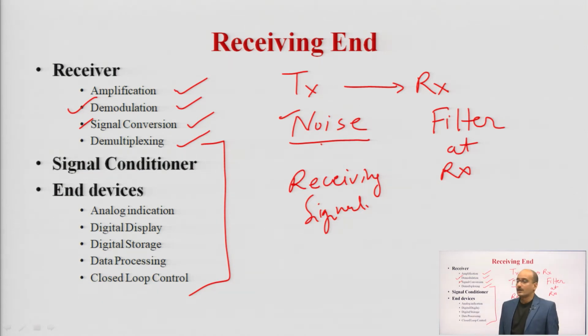So, in signal conditioning and then demultiplexing, what you are doing is that you are using the same channel for n number of inputs or outputs, so you perform demultiplexing, because now you have to select a particular channel at a particular point. That is why, as per the definition of demultiplexing, it is one input, many outputs, and one particular output is selected as per the select line.